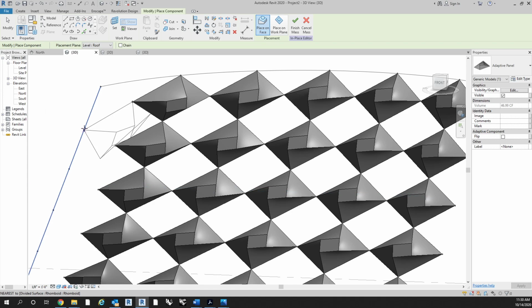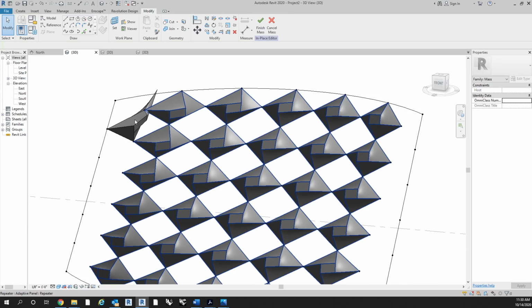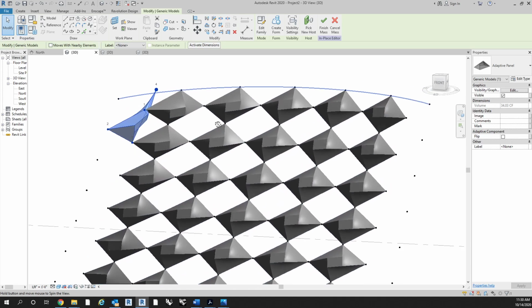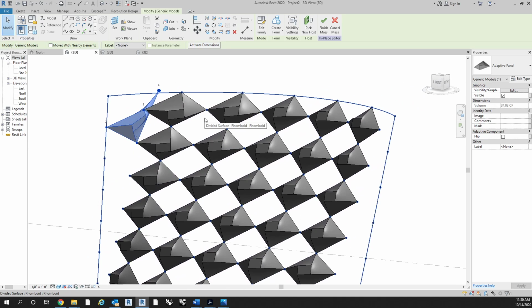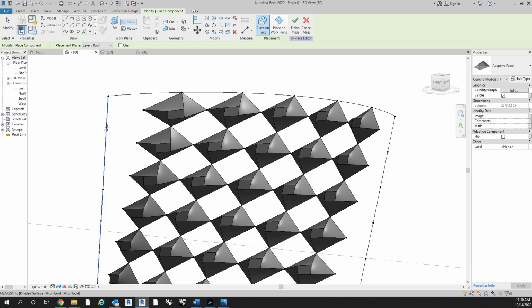Make sure that you're selecting the node once again. If you select, because you can kind of select off the face like this, and then it will still place, but it will be obviously weird, and it won't adjust. If you end up manipulating the surface again, it won't update to it. So make sure that when you're placing these, you are selecting the nodes themselves.